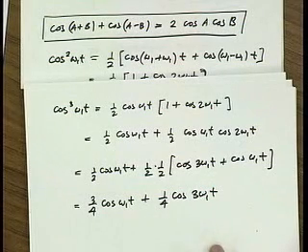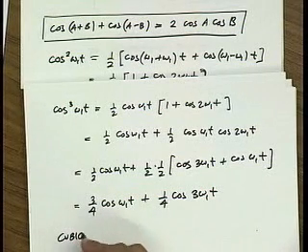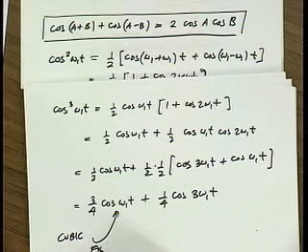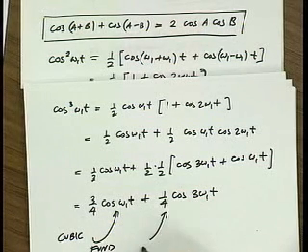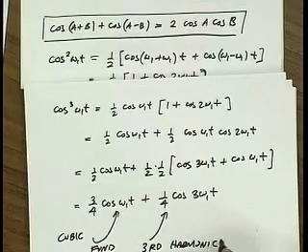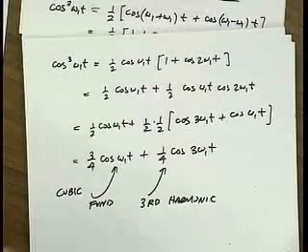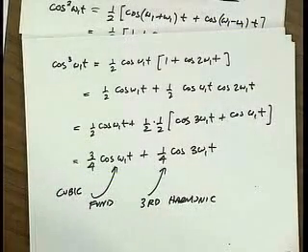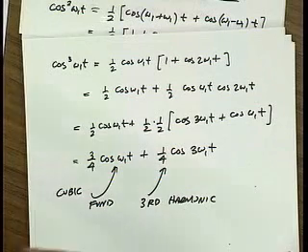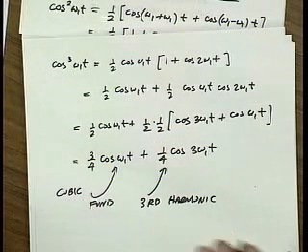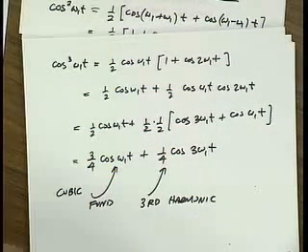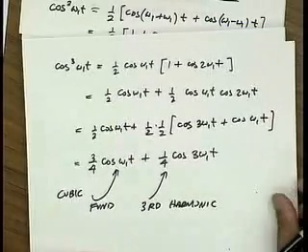And so we see that cubic will generate fundamental and it will generate third harmonic. And last lecture, what we proved was more generally that any even power will generate even harmonics, right, including DC, and any odd power will generate all odd harmonics, starting from the fundamental. Okay, so that's a quick recap from last lecture.